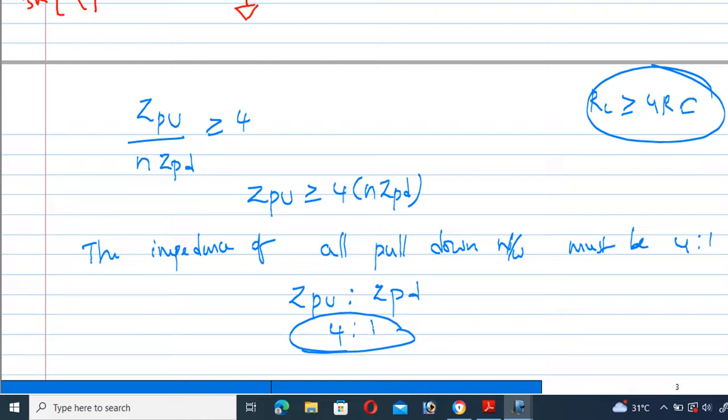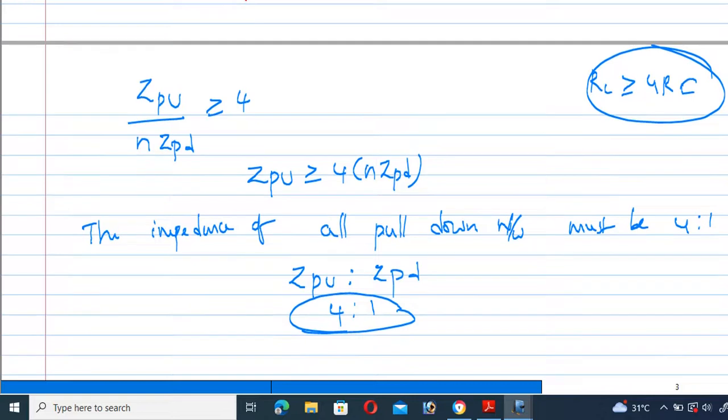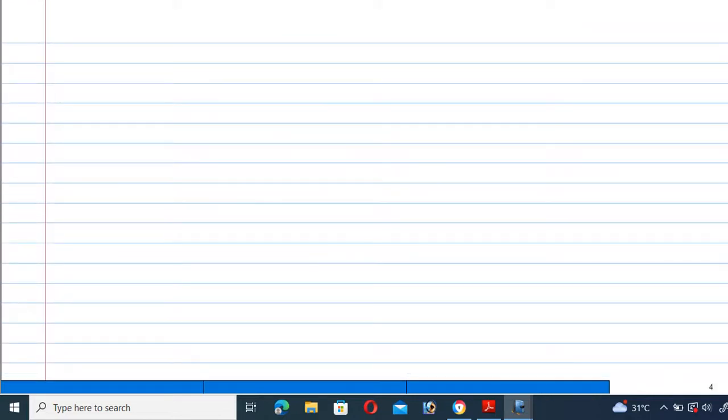It may be noted that not only is one pull-up transistor required for the input of the NAND gate stage, but the size of the pull-up transistor is also adjusted to maintain the required overall ratio. So here not only the total number of devices matters, but we also need to adjust the size of the pull-up device, which is a very important criteria.